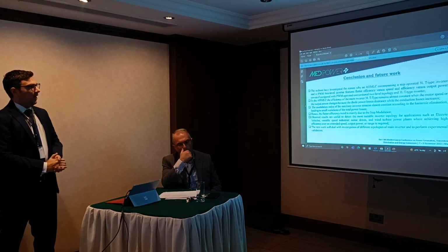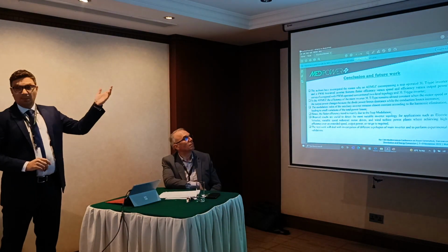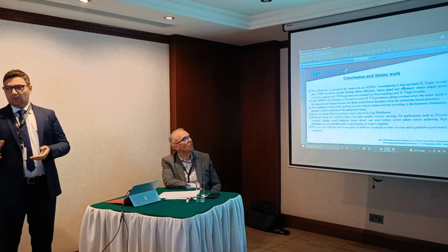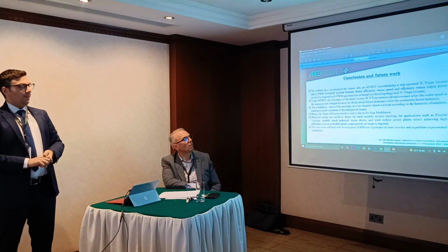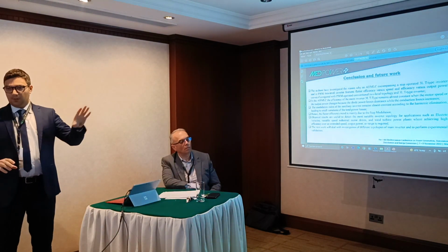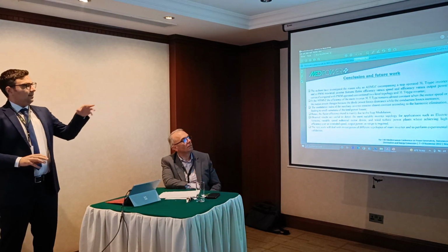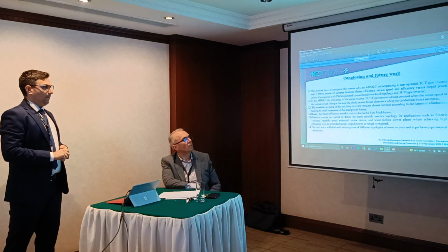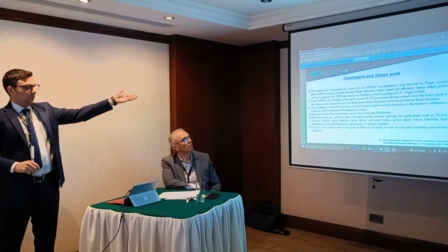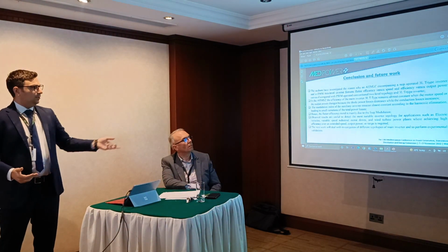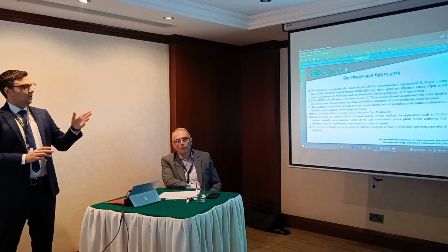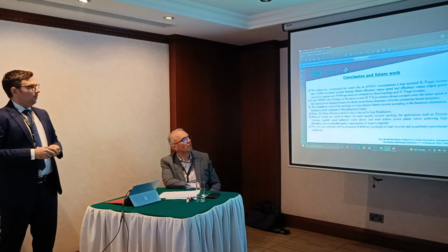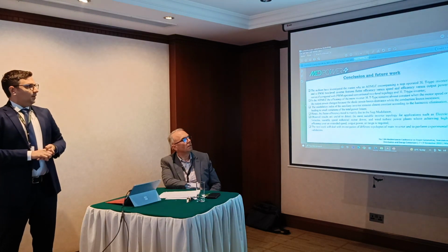In conclusion, I investigated the reason why the asymmetrical multilevel converter has a flatter efficiency diagram compared to the 2-level converter and 3-level converter. And from these preliminary results, because these are preliminary results, it seems that the flatter efficiency trend is mainly due to the step modulation. This is important because it's possible to detect the most suitable inverter topology for an application, for example, electric vehicle, variable speed induction motor drive, wind turbine, where it is required to achieve high efficiency for extended speed or power and so on.